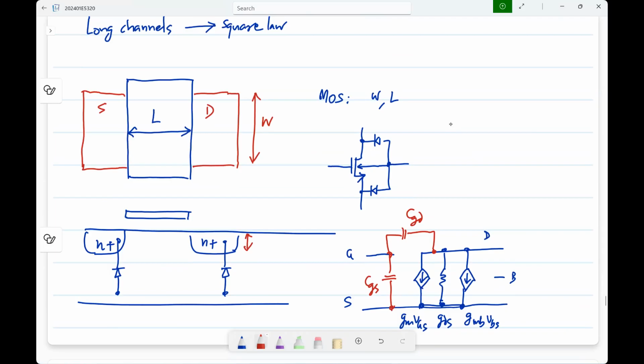That is, you have some metal connected to this and some other metal connected to the drain or the source, and because they are next to each other, you can have capacitances. All these will have to be modeled. Okay, so there will be a lot of parasitic capacitances, and there will also be the reverse bias capacitances of these, which will basically go from, this is CDB and this is CSB.